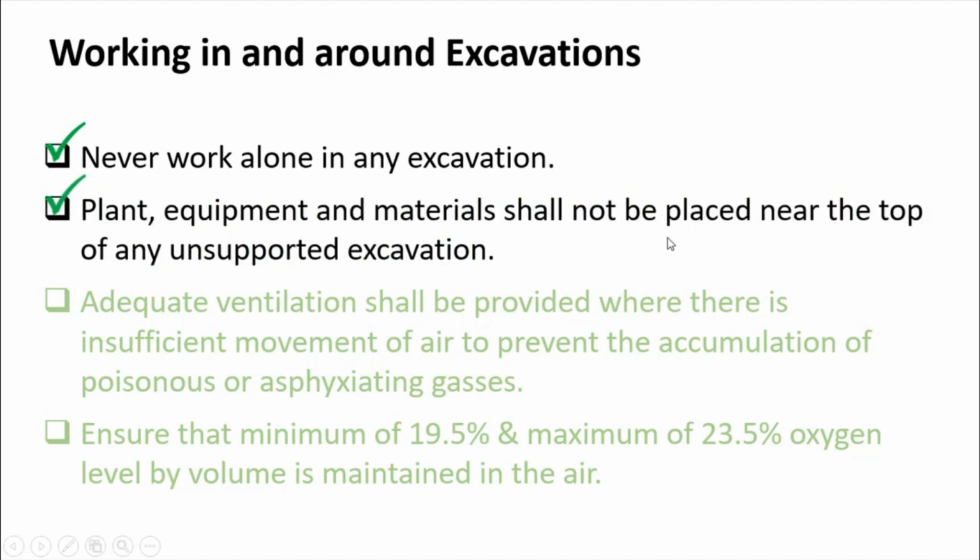Plant, equipment, and materials shall not be placed near the top of any unsupported excavation. So this is very clear. When you put plant, equipment, or materials on top, it will introduce additional load to the wall of the excavation, and then the excavation may collapse.